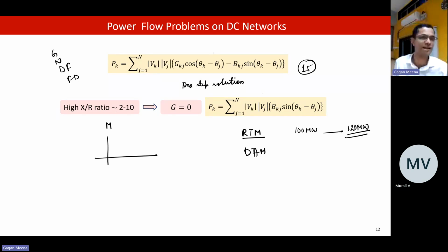going to the power exchange to buy electricity. They are buying energy for each time block. If they are short of energy, they buy, or they can even sell if they have excess. So which generator will generate how much? Which distribution company or consumer is going to get how much electricity? That is known after solving a problem. It is called bid matching.